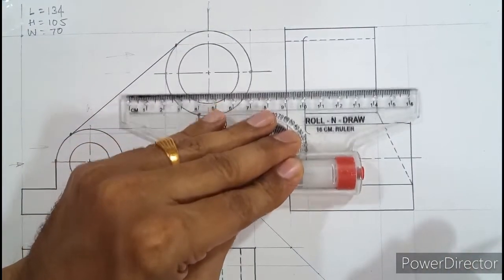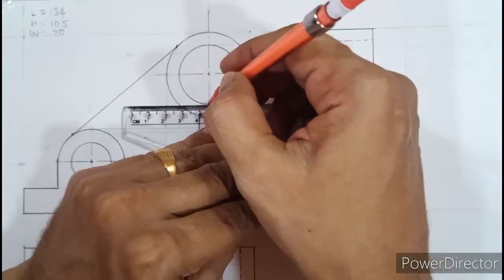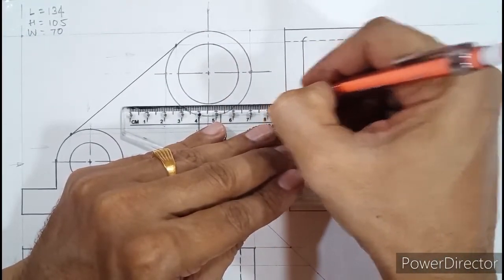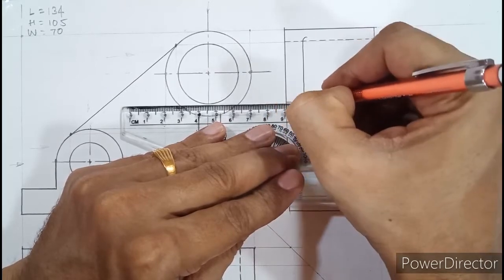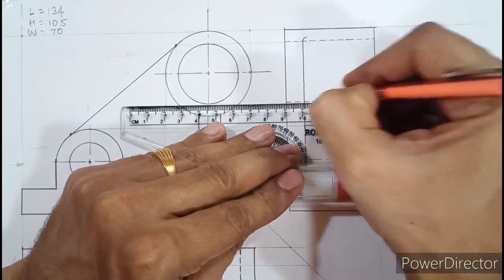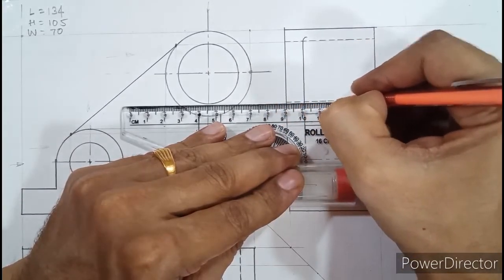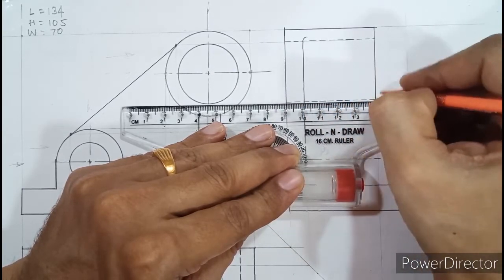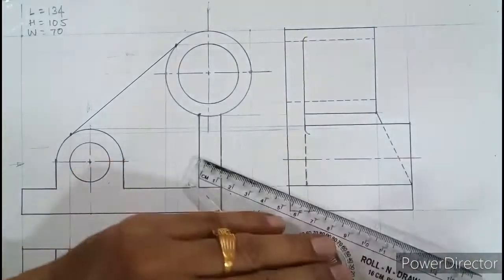So this is the top boundary of the circular surface. Similarly, the bottom boundary, we need to complete that here. So hidden line should be double trace, neatly drawn, less gap and more length. And it should be perpendicular, all four sides should intersect.